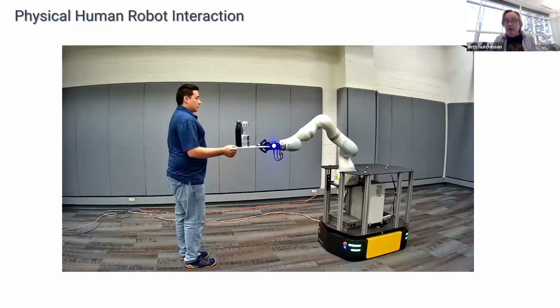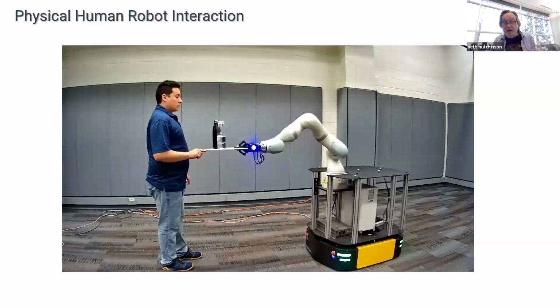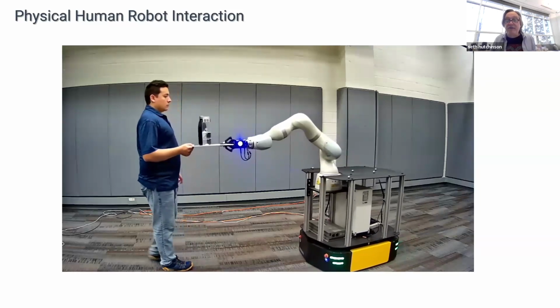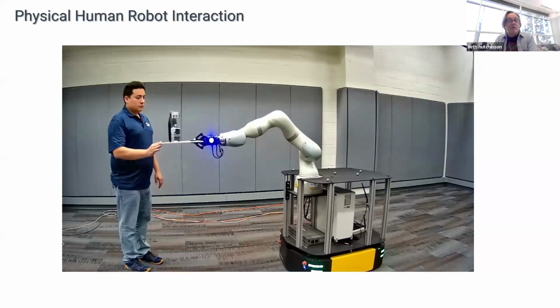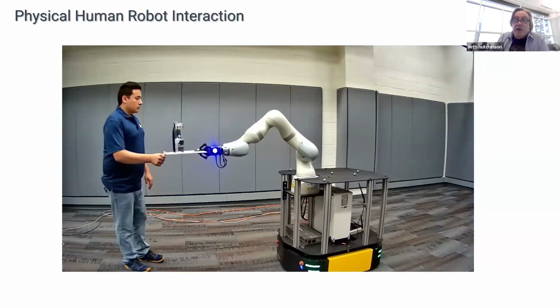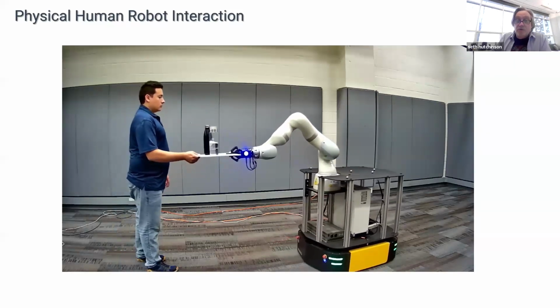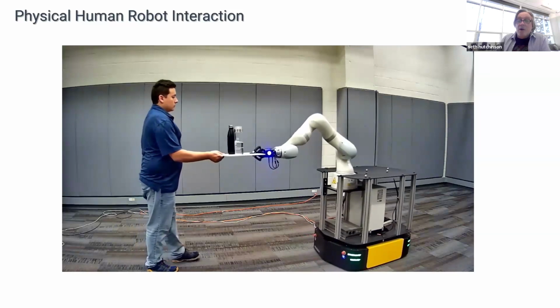And using the low-level control where the barrier functions are enforcing, in this case, the orientation of the end effector, and the control Lyapunov function is implementing an impedance-based controller, you can move this thing around pretty easily while enforcing the constraint that you never spill the water.